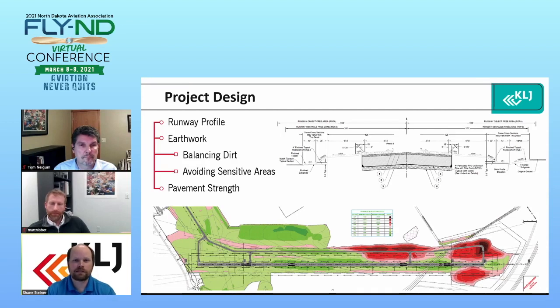We also had some spots with a really high water table and some where it wasn't an issue. So when we looked at chemical stabilization, blending in lime or cement, versus mechanical stabilization, the recommendation of the geotech engineer, and what we ended up going with, was the mechanical stabilization route, where when we got to those soft areas, we did an additional 2 feet of subcut.